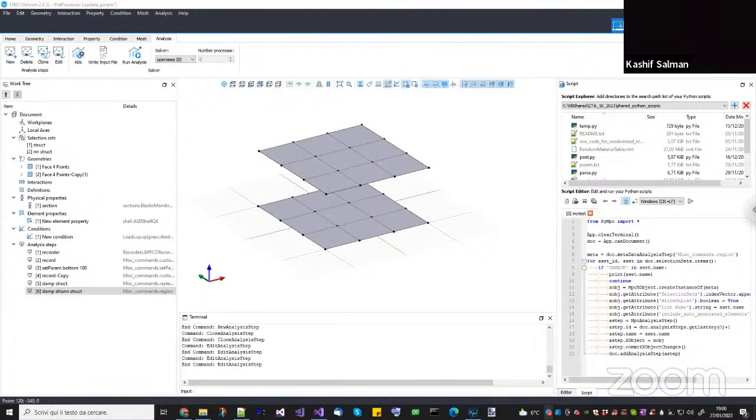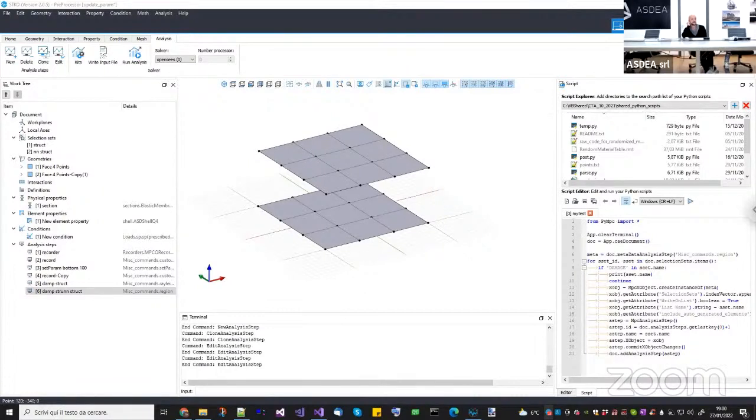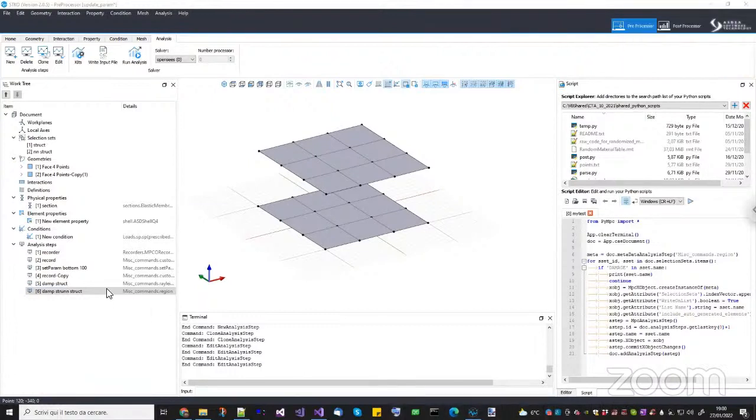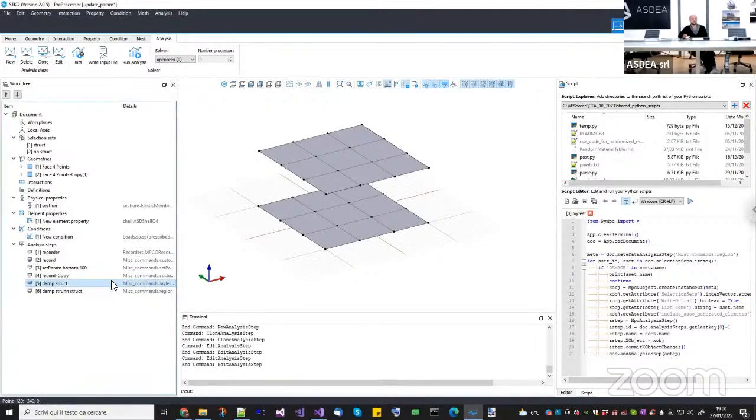Yeah, if using Rayleigh damping on different components with different Rayleigh damping parameters is fine, you can do it with OpenSees. If Rayleigh damping is not fine at all, even if you split it with different parameters, in OpenSees you have another kind of damping, like modal damping, okay? But it's not documented, so probably we will do a webinar on that later on. The problem is that there is no documentation on that. Modal damping could be a solution for that.